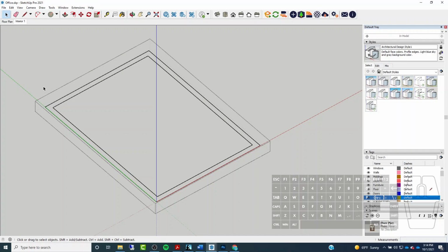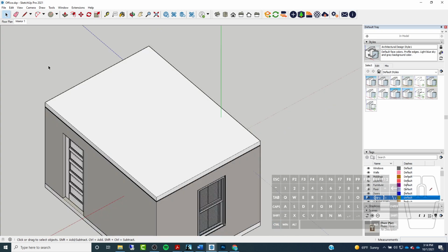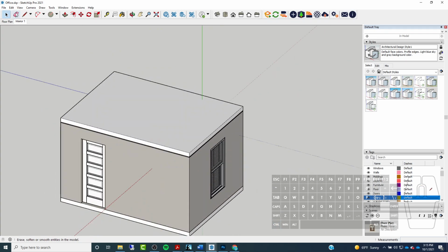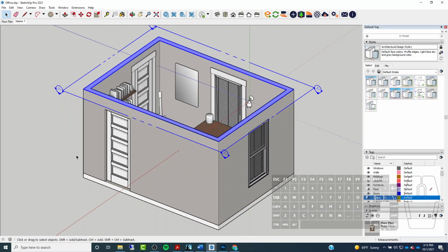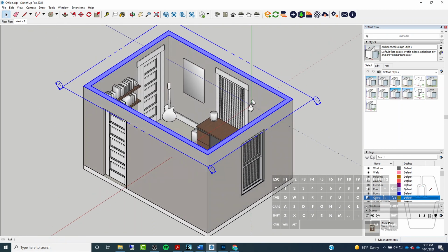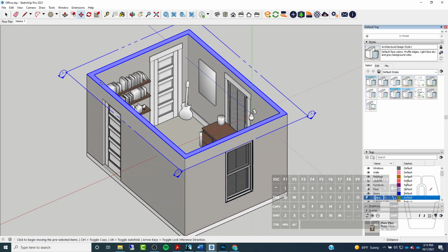You can see it cut through the walls, and it basically just created an outline of the shapes that it went through. That's pretty cool because if I turn my plane back on, you can basically turn a SketchUp model into an AutoCAD floor plan and export out an AutoCAD plan into something like Revit.